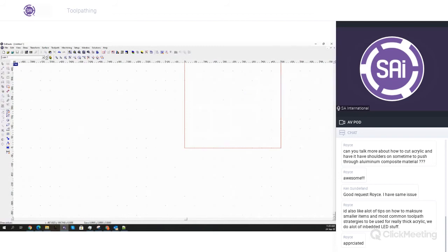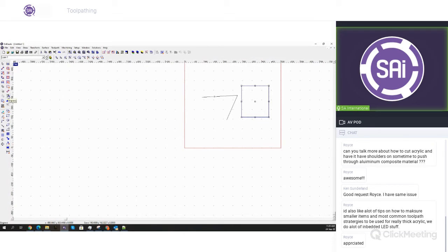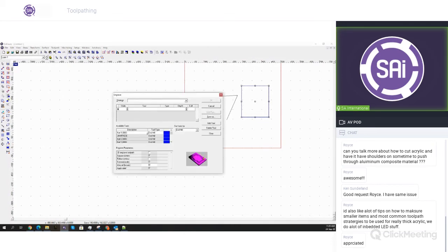Going into the engraving strategy, engraving strategies can be added to both closed shapes as well as open shapes, while the island fill and the hatch fill you'll only be able to add to a closed contour. Going into the engraving here, we'll either do that with an engrave tool, but I like to use conic tools for this as well.